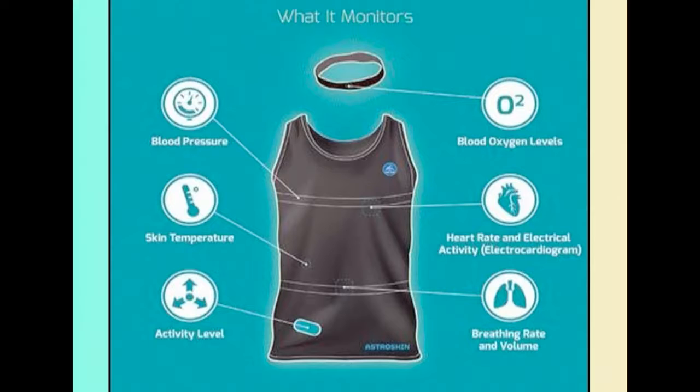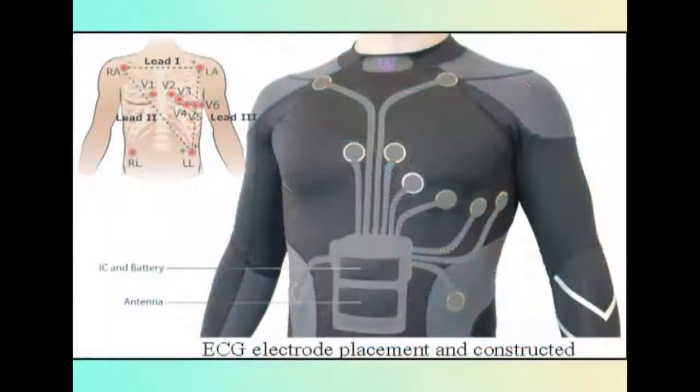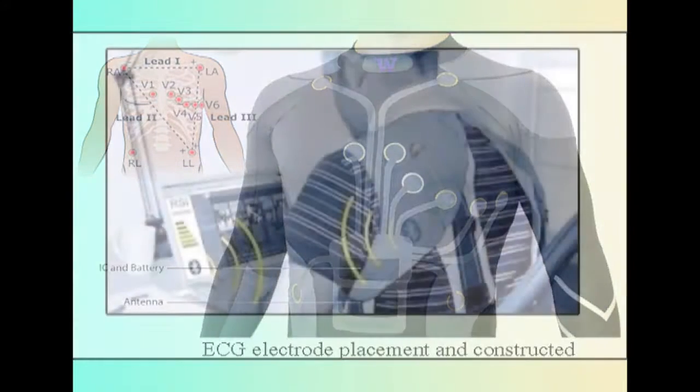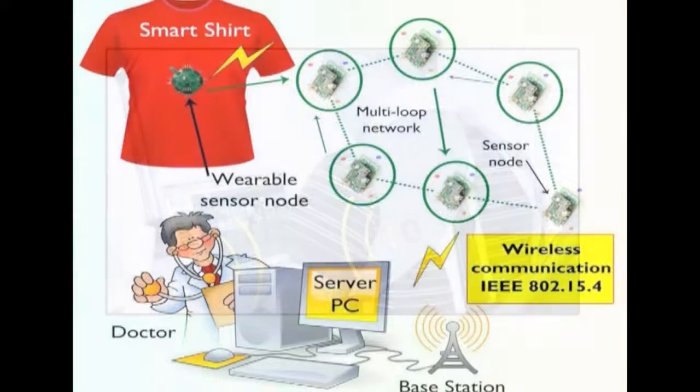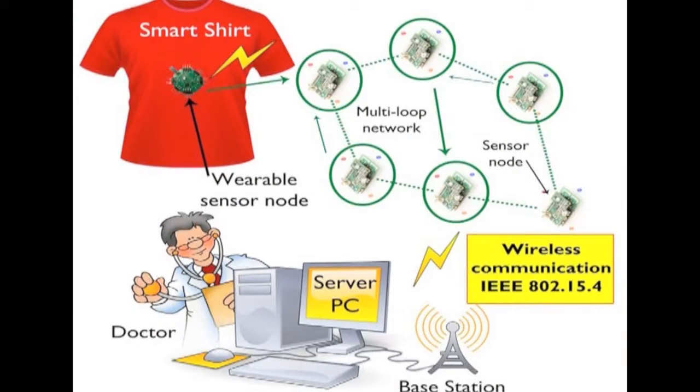piezo-resistive yarn-based fabric, electrodes realized with metal-based yarns, a sensitized vest including fully woven textile sensors for ECG and respiratory frequency detection and a portable electronic board for motion assessment, signal pre-processing and Bluetooth connection for data transmission. The wearable sensitized garment measures human heart rhythm and respiration using a 3-lead ECG shirt. The conductive fiber grid and the sensors are fully integrated, which means knitted in the garment of the smart shirt.